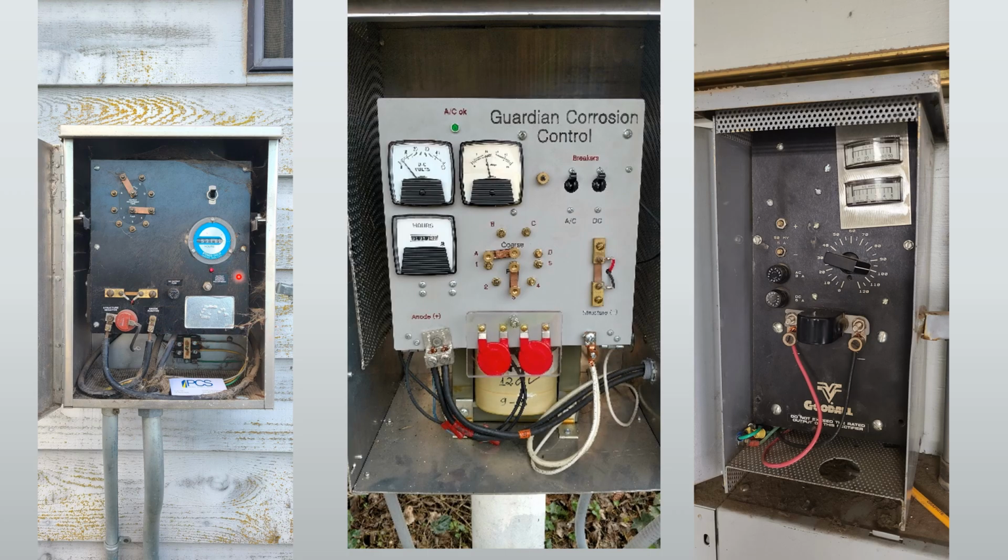This unit was so old that the markings had started to come off of it, but again, the basic tap and bar, pretty old. This looks like an old lightning arrestor system that was installed. You can see the dust buildup on these units. That's why it's good to hit them with some compressed air. Make sure that you're staying away from the live wiring in the back. That is hot. The switch on the front will control to take off the DC power. So these guys will be dead, but you'll still have live 120 in the back.